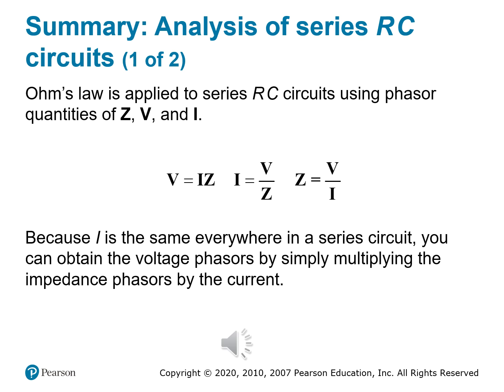Imagine trying to analyze a waveform that's always changing. Phasors just make it easier by capturing the peak behavior, the magnitude and phase, in a single, clean arrow, right? It freezes time so we can do math on alternating currents. In the RC series circuit, once you know the impedance triangle, the Z and the angle theta, and the current denoted by I, you can calculate each voltage.